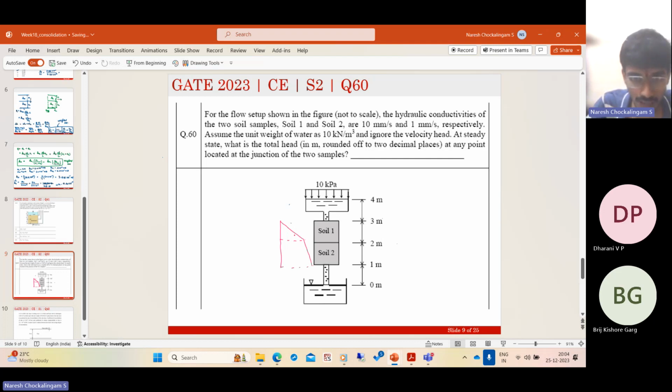But if you have homogeneous soil, if they are asking what is the head here, you can just take the average of these two values. Here it is not continuous, so you cannot do that. Anyway, let us solve this problem. So this is the problem where you assume 1D flow as usual. Assume 1D flow. You assume Darcy's law. And you also assume the pipes are frictionless.